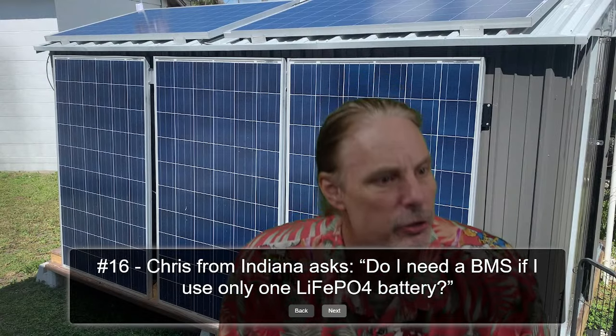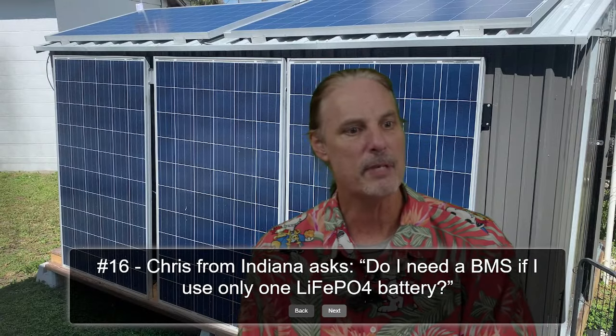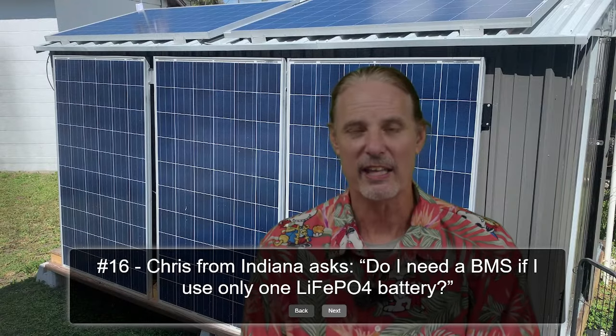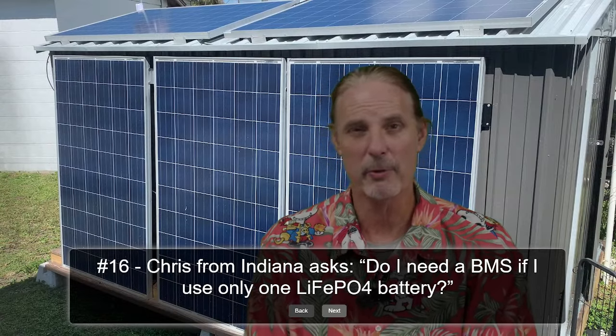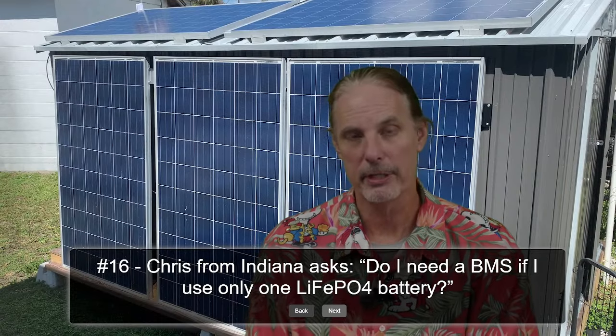I'm going to move on to Chris from Indiana. Chris asks, do I need a BMS if I use only lithium iron phosphate batteries? And the answer is, the lithium iron phosphate battery should have a BMS. And if you are building a DIY battery without a BMS, I would say no, stop, put in a BMS.